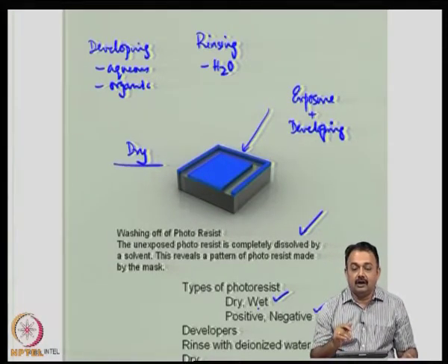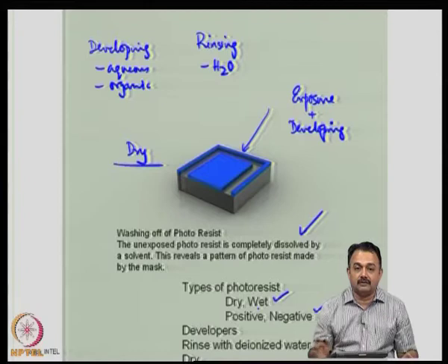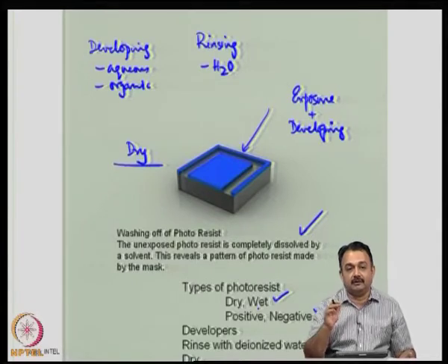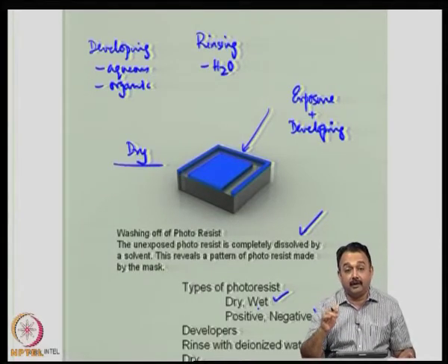When to use a positive mask and when to use a negative mask depends on what kind of image area of the circuit you need to have on the surface of the wafer. It can be the first step or the nth layer. Okay. So, depending upon the interconnection pattern and depending upon the availability of certain chemicals and equipment, you have to carefully choose the photoresist type.